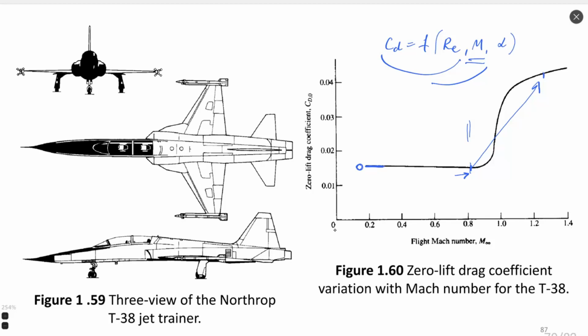We do an experiment here and we measure the drag coefficient at this point of our airplane. What does it mean? It means that we do not need to test at other points until the transonic regime. It will have absolutely the same value of drag coefficient, independent of Mach number. So we can reduce the number of experiments significantly.